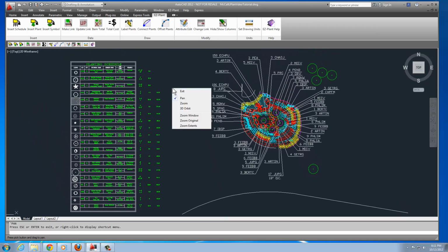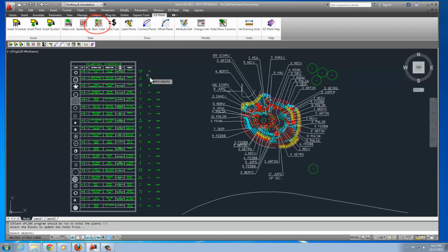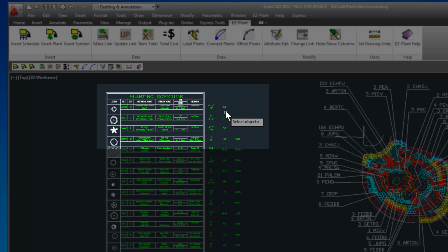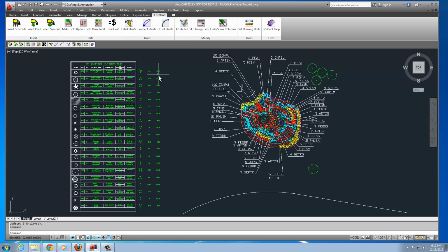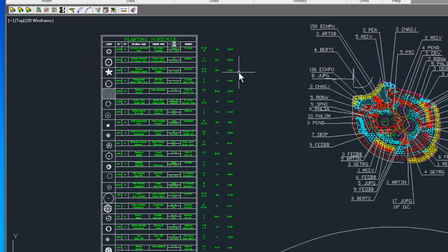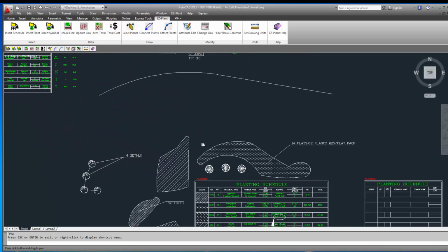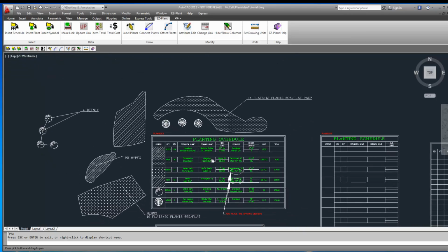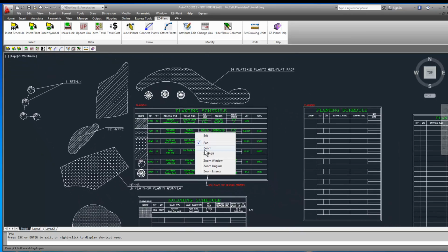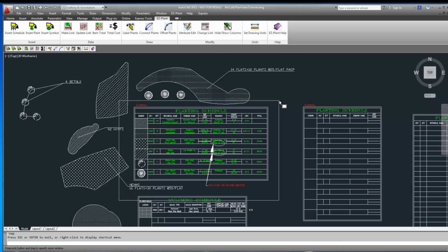Before we quantify plants, we need to make sure all the plants are linked and totaled before the cost estimate is finalized. When we selected the schedule options, we chose this plant schedule because the price column can be hidden. The prices still show up to the right of the plant schedule to benefit the designer, but they can always be hidden. We will total the plant schedule that contains only 6 plants for the cost estimate of ground covers to illustrate how ground cover plants in flats quantify.